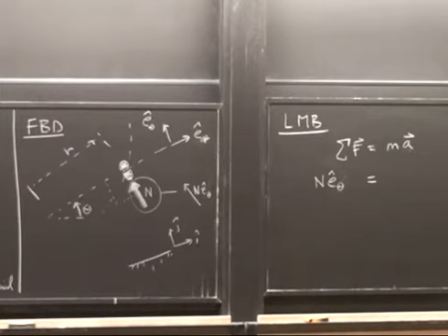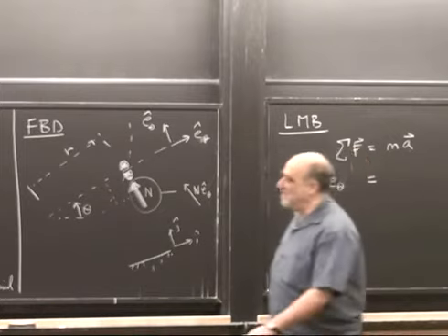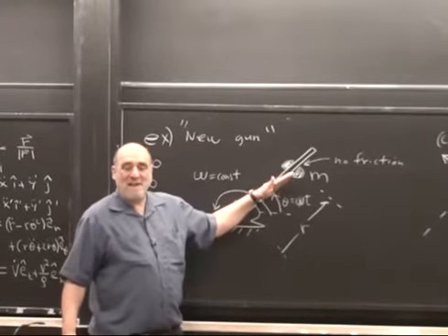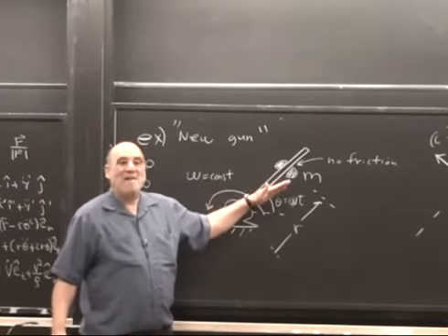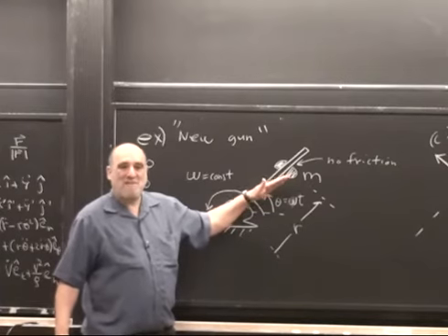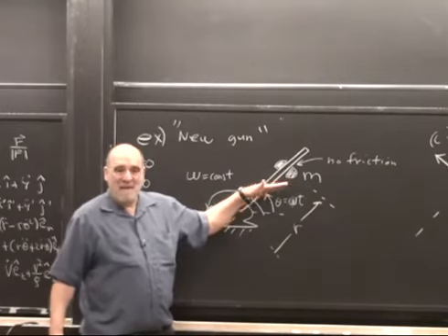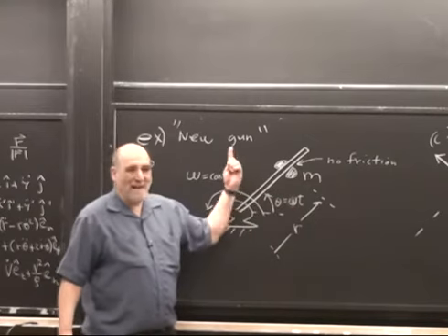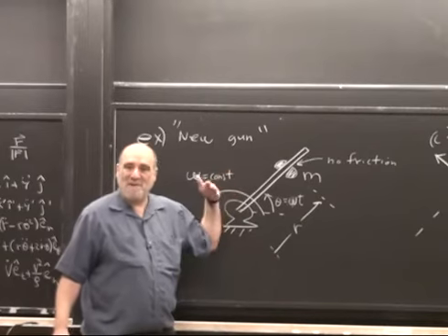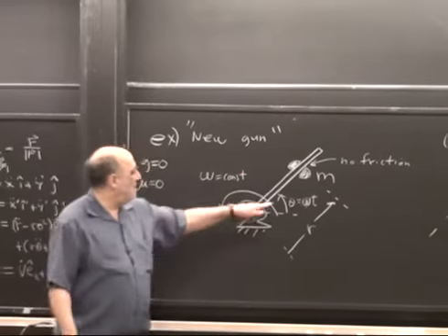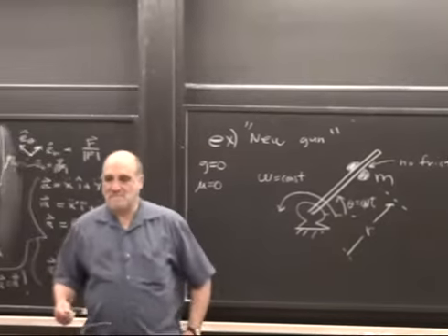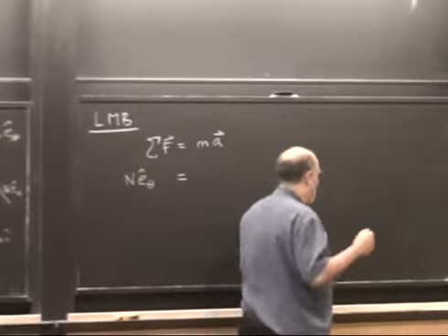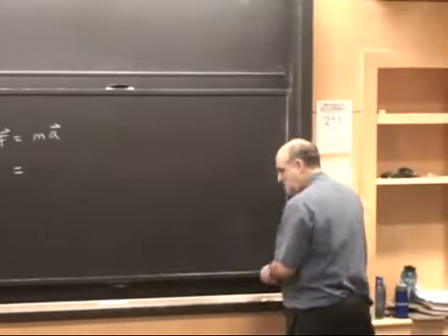This is a setup for polar coordinates. Why is it a setup for polar coordinates? Because we're told what theta is as a function of time. We've been given a kinematic constraint, and we can eliminate that constraint implicitly by just representing things with r and theta. If we represented things with x and y, we'd have to add that description that it's always on this radial line in x and y coordinates. In polar coordinates, it's very simple. We just say theta is given by this equation. So, of course, this is a problem that's set up for polar coordinates. It's like the best problem for polar coordinates.